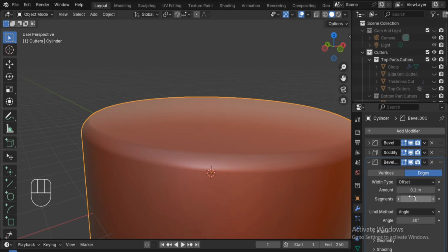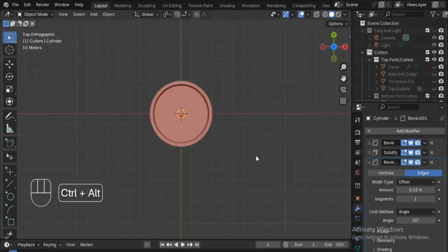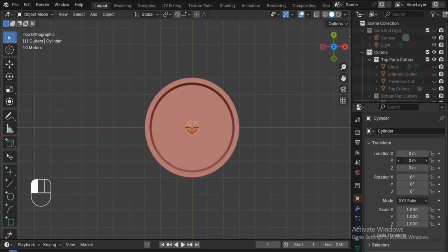I've added a solidify modifier on the modifier stack and made the thickness 0.1 millimeter. Always add some thickness to the models. It just cannot be a flat thing. It's never 0. It's either 0.1, 0.2, something on those lines. Better if 0.2 or above. For 3D printing, 0.3 is a stable one, 0.5 is a stable one for normal printers. And for high quality printers, you can go down to 0.1 or 0.2. However, that is not usually recommended for normal 3D printing systems.